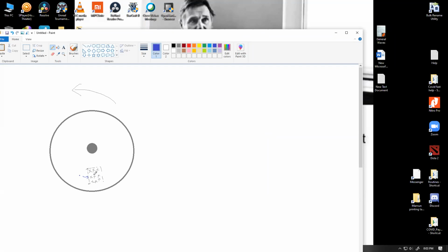So whenever the electron will enter over here, along with the rotation of the disk, this magnetic field is going to apply some vertically downward force onto this electron. So this electron will try to get out through this side. So if the electron is trying to get out through this side, there will be a conventional current produced vertically, in the opposite direction. Let me draw this with purple. So there will be some upward directional current produced within this segment, because electrons will be leaving out from the bottom. So conventional current will be happening in the upward direction.